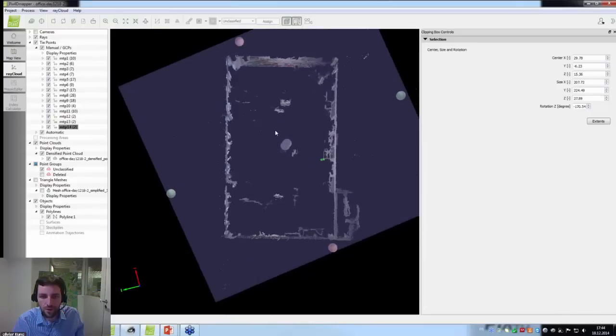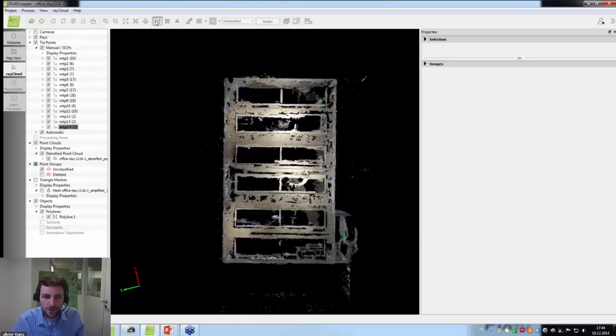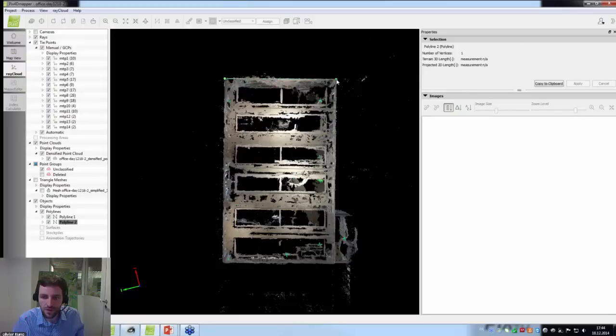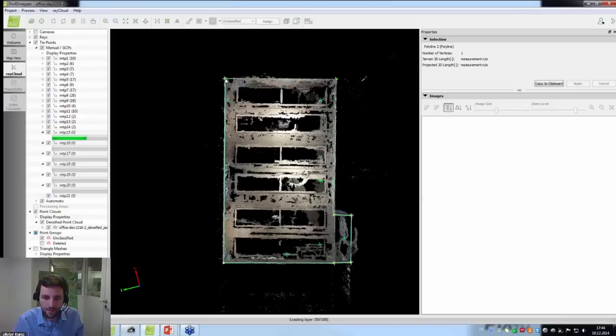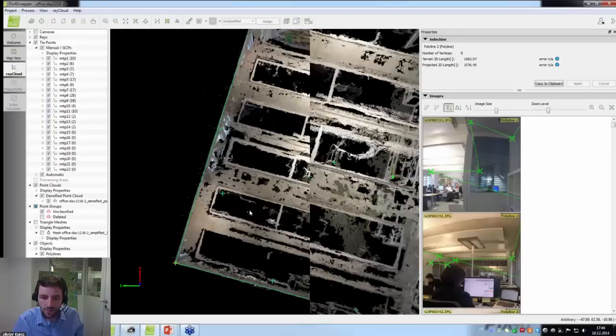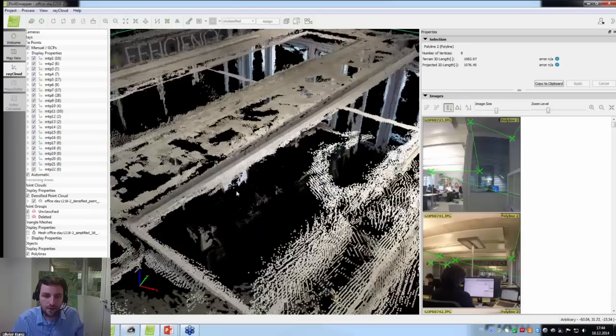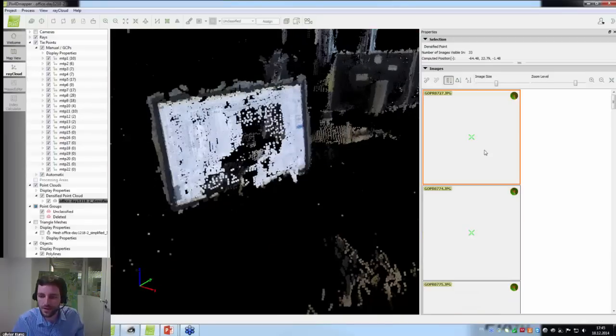And now you have all the walls on which you can start annotating surfaces and doing the measurements of the full geometry of your room and drawing simplified CAD models from it. If you needed to pick one single point of this dataset to get something even more accurate, you always have the option to go back using the ray cloud and the nice tools that we have there.